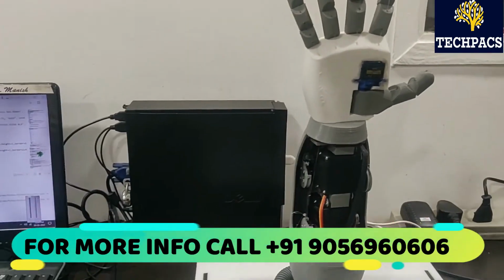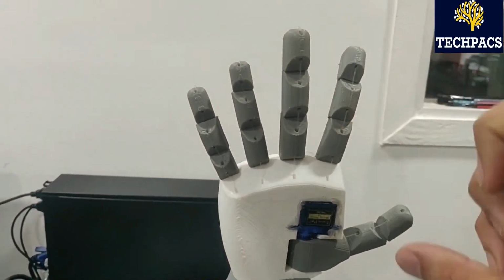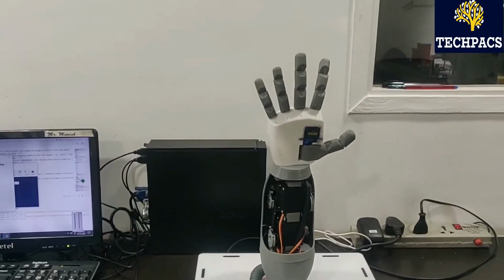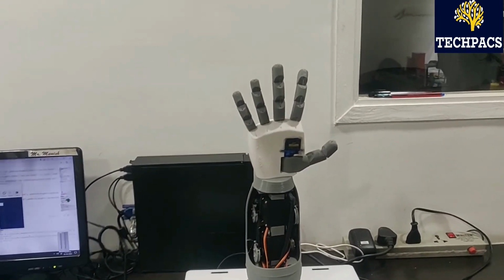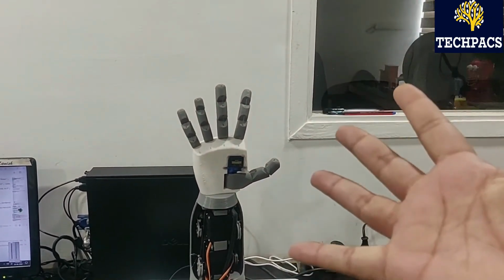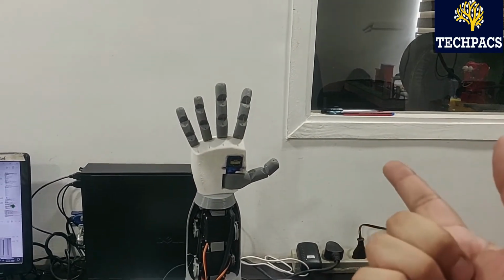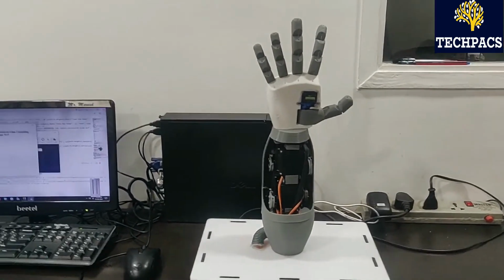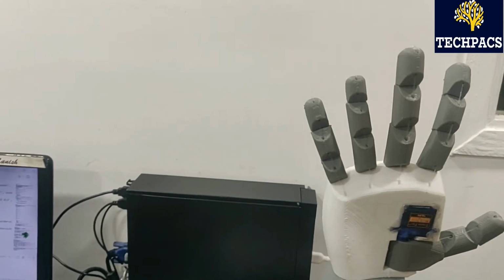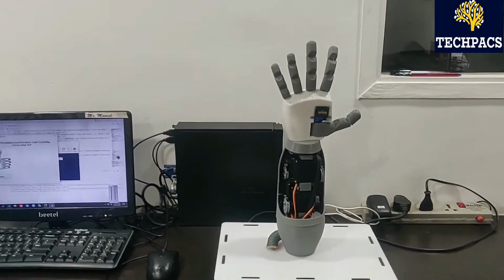The motors that we have used here are all servo motors. This is because we have to make the movement at some particular angle of these fingers, since we have to make movement of the limbs of the fingers. So this cannot be performed using DC motors that keep continuously rotating, as we can see that we have to make movement of the fingers as shown in the video. This is possible only using the servo motors, as they provide rotation, or we can say movement, at some particular angles only. Therefore using servo motors would also provide a more realistic look to our project.